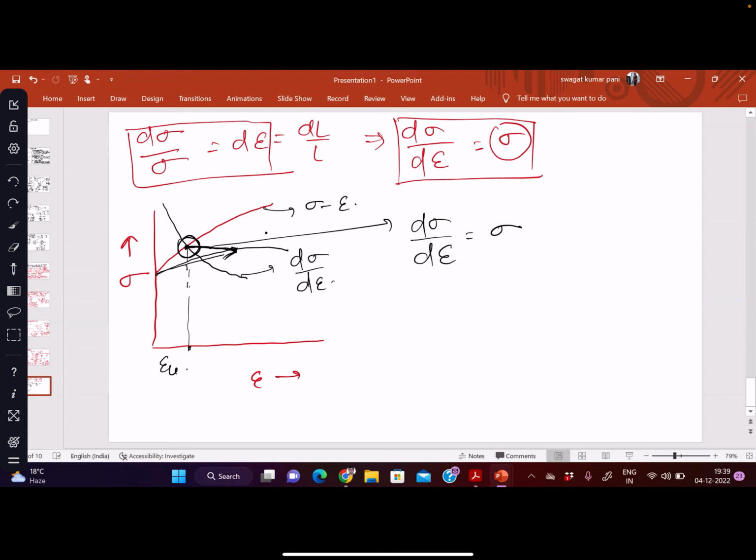Because as I said, the true stress curve is always to the left. So if we have some point in engineering strain here, that will be reflected in the true stress strain curve here. If it is here, then it will go here like this. Okay, so this amount is the true stress up to the highest load. True strain.